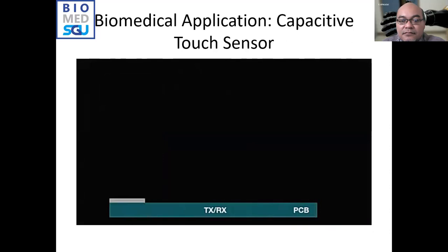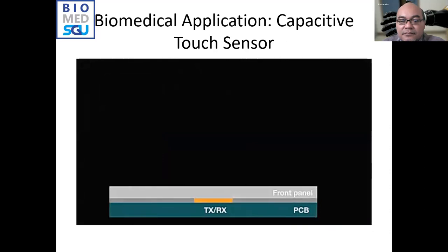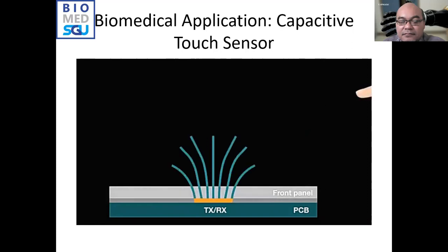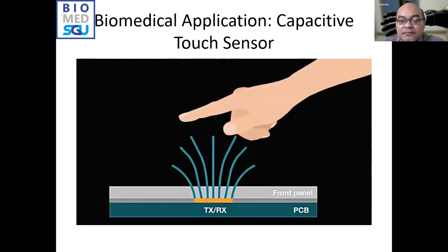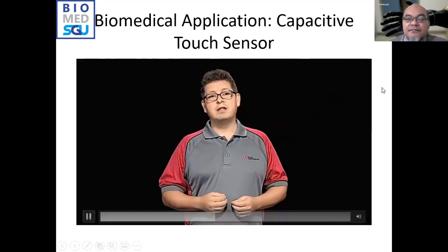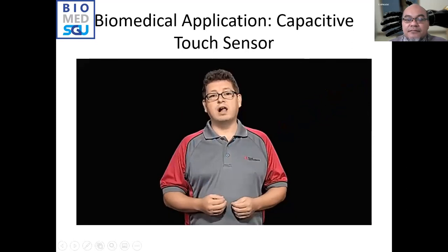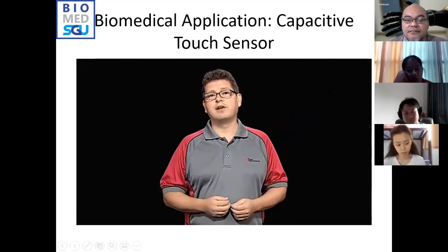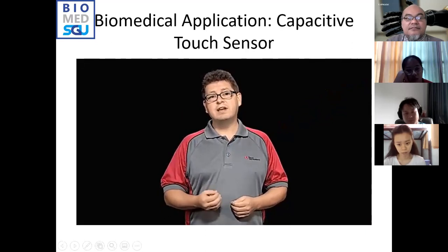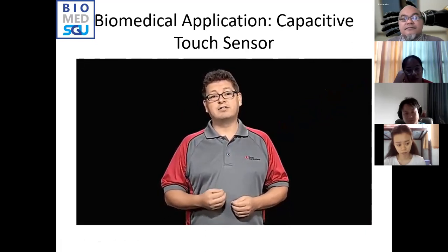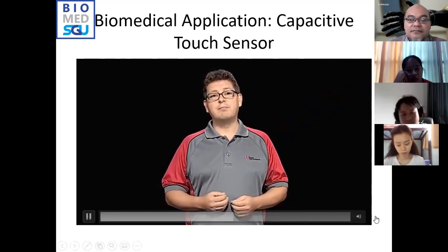In a traditional capacitive touch design, the touch sensor is connected to an MSP430 MCU and emits an E-field. When a human finger comes into the E-field, a change in capacitance is detected and a touch is registered. This mechanism works well with plastic, glass, and other non-conductive overlays. In the case of a metal overlay, the sensor E-field is destroyed, making it unusable.